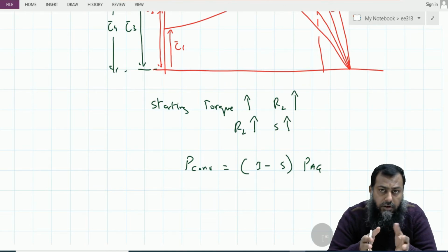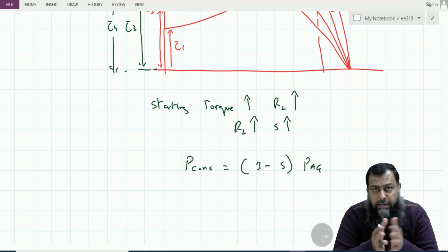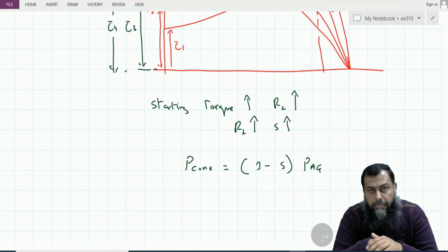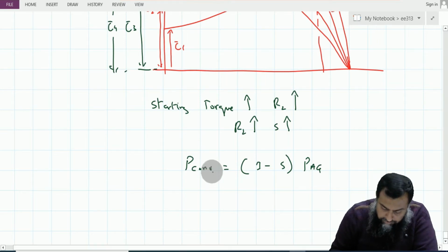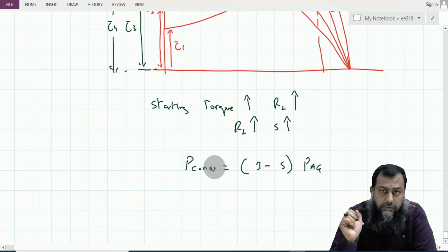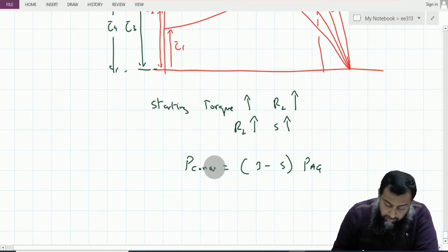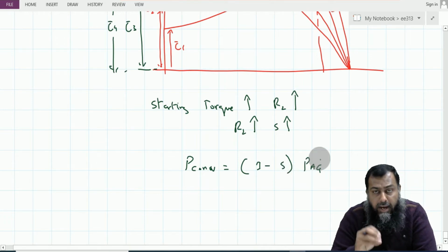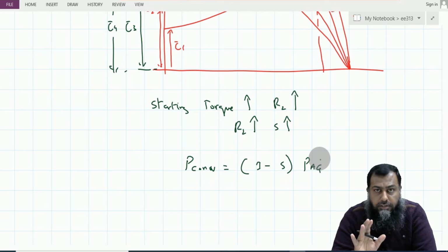After all, the efficiency of an induction motor is the measurement of how much of the electrical power is converted into mechanical power. With the increase in the slip value, we are compromising on the overall efficiency of the converted power, P converted, and therefore we should always see the impact of the slip and the added resistances in a given machine to accomplish a given task, because a compromise between the two is required.